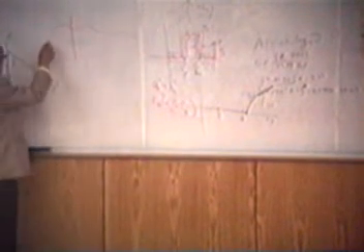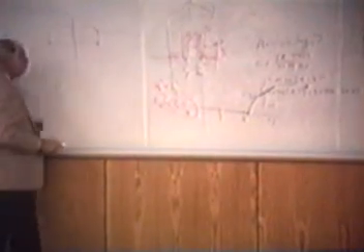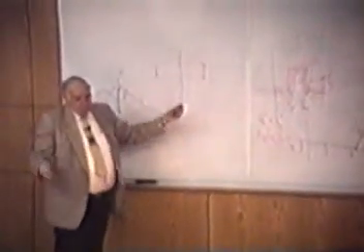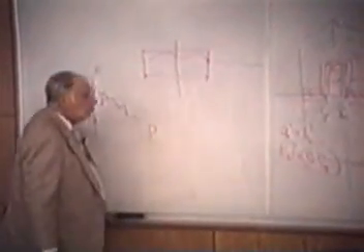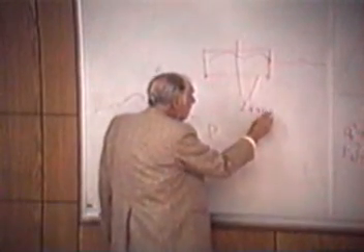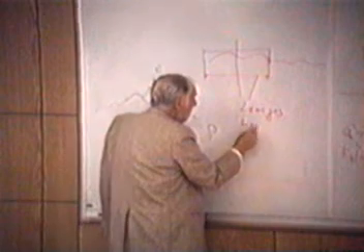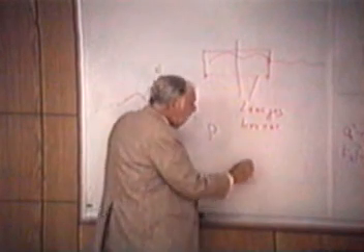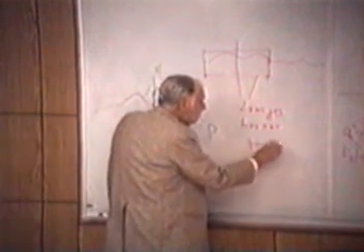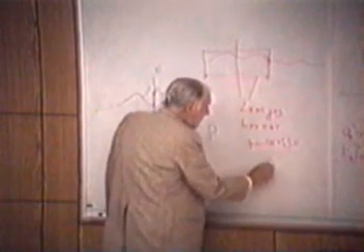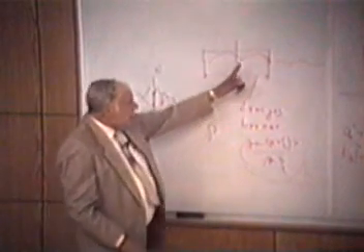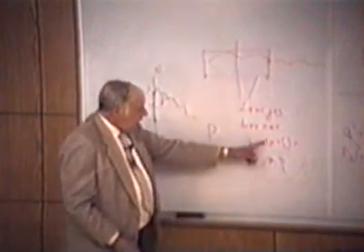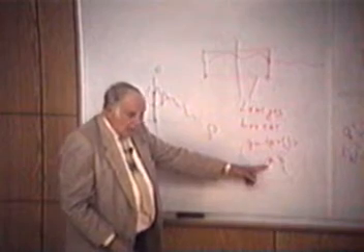You turn your equipment on and off, and I'll simply put it symmetric about the origin. You turn it on and off. That means you're looking at that through a square window, or if you want, boxcar. And you remember I derived a sine n plus 1/2 x over sine x over 2, and asserted every line in the spectrum here is smudged by that.